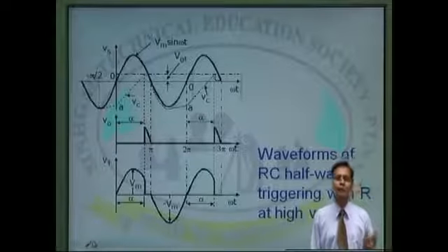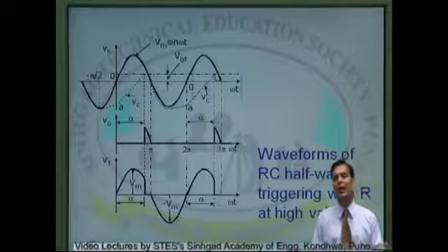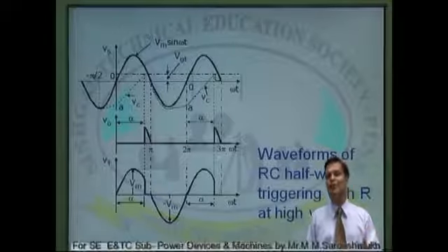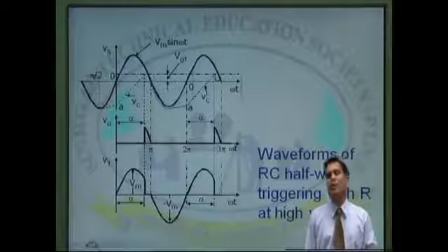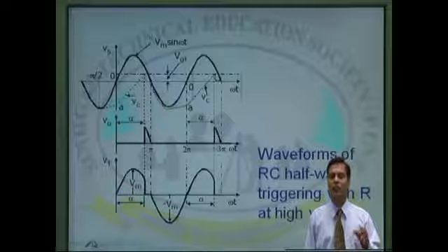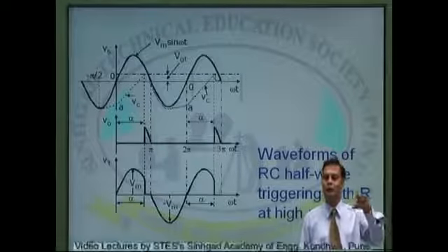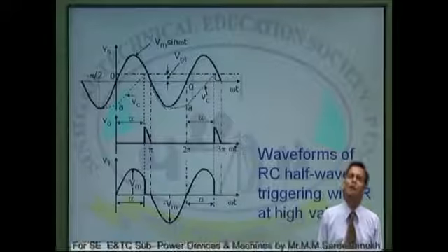And you are observing here the waveforms of voltage across thyristor and the output voltage. Again here you will find the same thing, that when SCR turns on, means whenever a sufficient amount of gate current is applied to the gate terminal of an SCR, SCR will turn on, and when SCR turns on, the positive voltage applied will be coming across load, and voltage across thyristor will be very small, that is nothing but the on-state voltage.